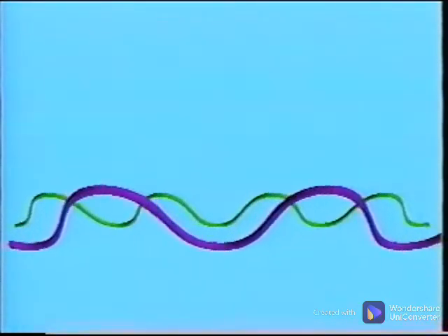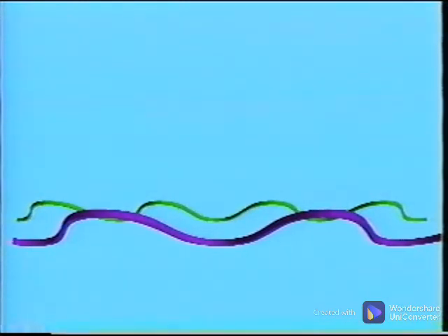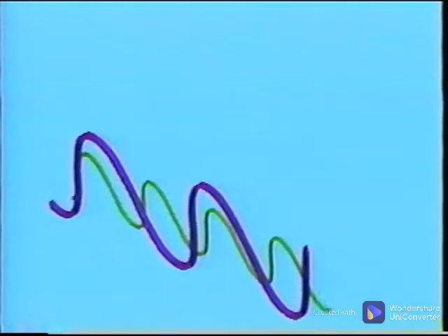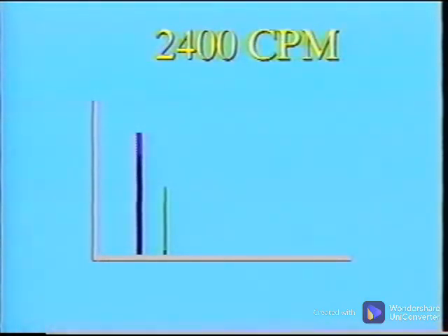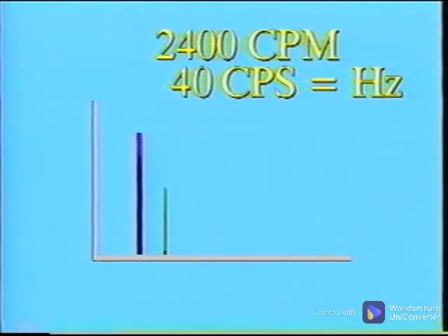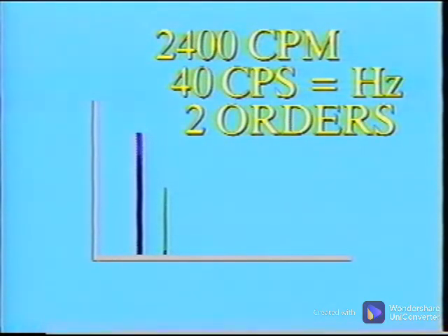The analyzer processes this waveform signal and actually separates the waveform into 2 individual sine waves. The calculations are performed for each sine wave, which has the net effect of viewing the discrete sine waves from the end, which is the spectrum. The frequency of this new peak can be expressed in each of the 3 frequency units and can be said to show energy that occurs 2,400 times per minute, 40 times per second, or 2 times during each shaft rotation. This 2 times peak is often called a 2-order peak.